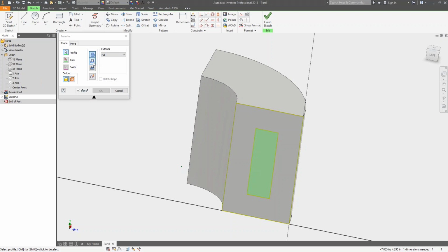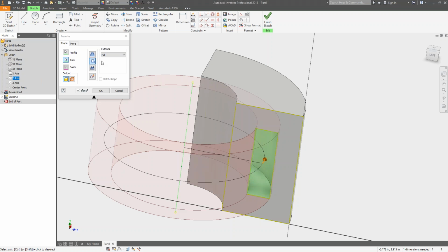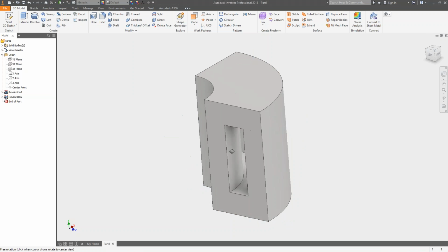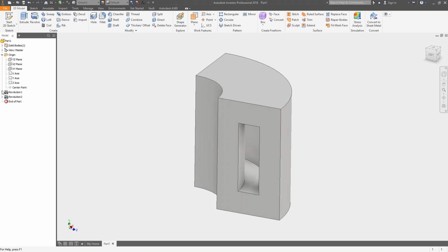So now what I'm going to do is a cut. I'm going to pick that axis again, and when I go to cut this, it's going to create that geometry and do that cutting operation. So what I have now, rather than one revolve with a more complicated sketch, is 2 revolves with relatively simple sketches, and that's, again, best practice, usually the way you want to go about creating your geometry. So the next one that I want to talk about, shoot, you got another question?